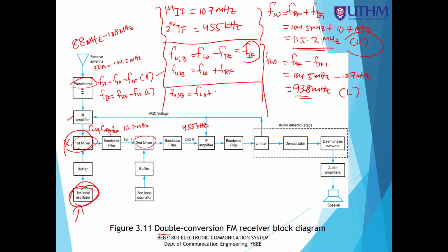is FLO plus FRF. So this is equal to 115.2 megahertz plus the frequency channel that I want to listen to, 104.5 megahertz.